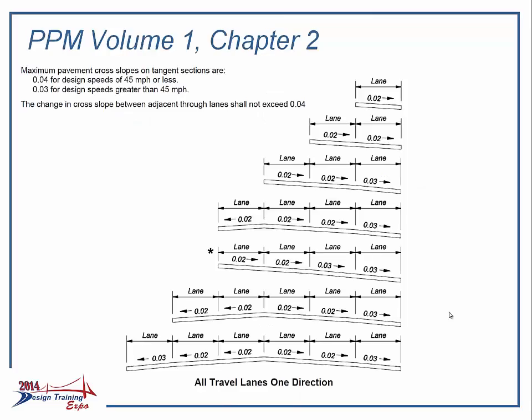The FDOT Plans Preparation Manual specifies the typical desired cross slope in a normal crown situation for single and multiple lanes. These values should be the design target cross slope when you're running your subassembly. The subassembly is also sensitive to super elevation and will retrieve super elevation when the section becomes super elevated.